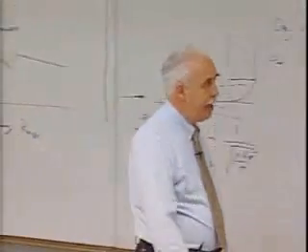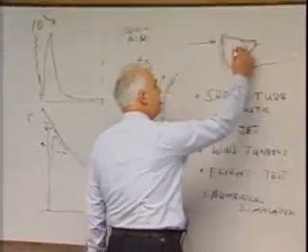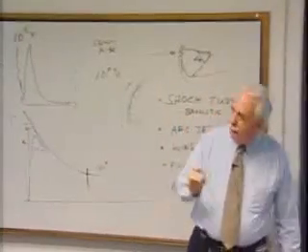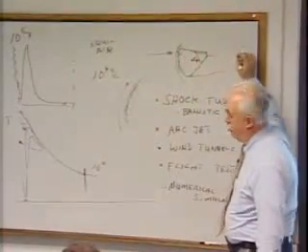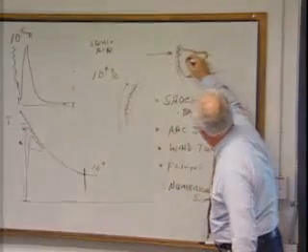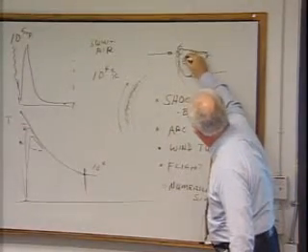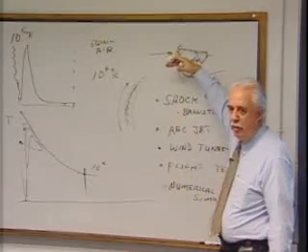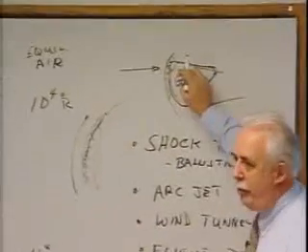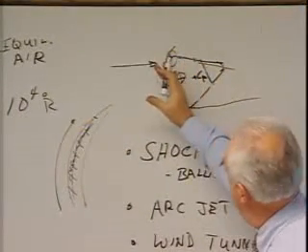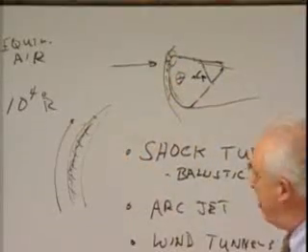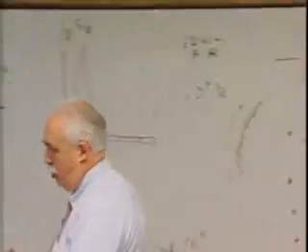In order to go to angle of attack, I have to take the center of pressure, which is basically the point about which the aerodynamic forces act, as if I put a string and pulled on that, right? And I want the center of gravity ahead of that, and now I've got a nice stable configuration. Not too stable because the control people want to do things with it, but stable from the standpoint of not having to fire RCS jets or have control surfaces and all that type of thing. That's how we designed Apollo. It worked very well.